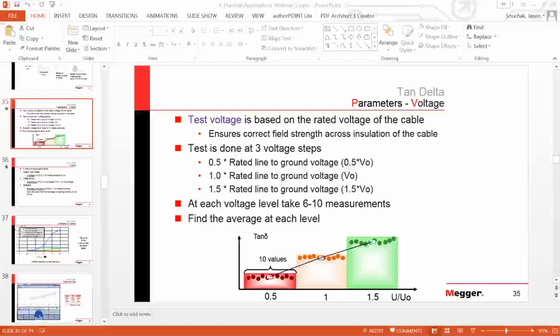So that's why the temperature is certainly one of the fundamental aging parameters you have that affect the insulation, and you might also have a combination of temperature but also mechanical, because as you well aware of, if you have a lot of changing temperature from changes in loads, you get also, let's say, thermal expansion and contraction. So you have also now the mechanical aspect of aging, and so sometimes some cables are not always all the way buried.